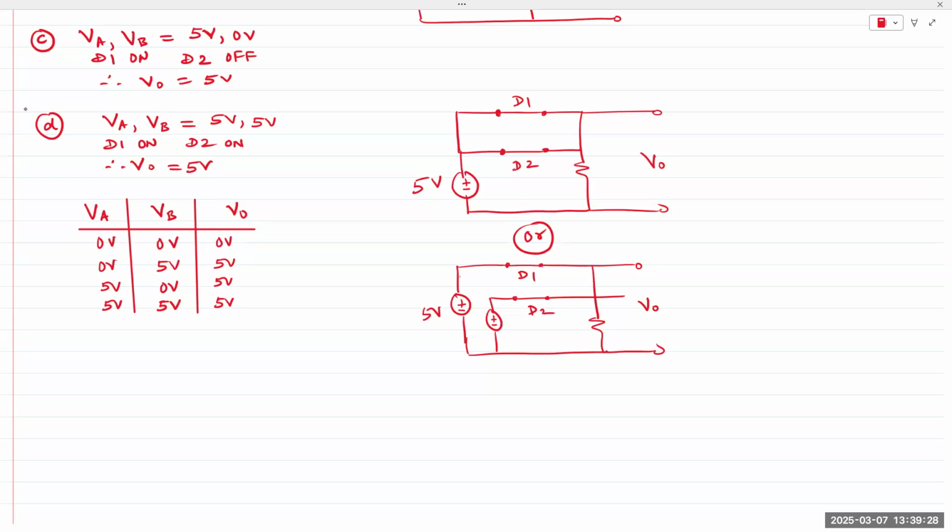I'm just stating random numbers in that case. Basically, a small top portion is logic high, and a small portion of the bottom is logic 0. So even if the transistor or the diode gives you 0.2 volts, it is still considered logic 0, and if it's 3 volts, it's still considered logic high.